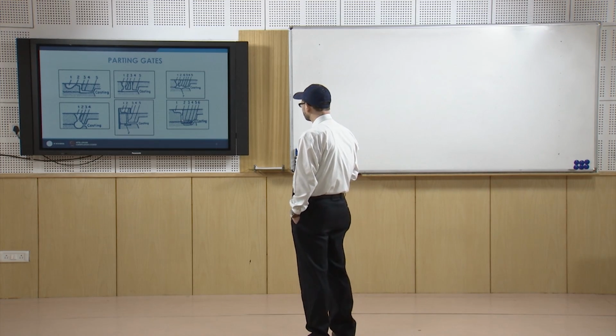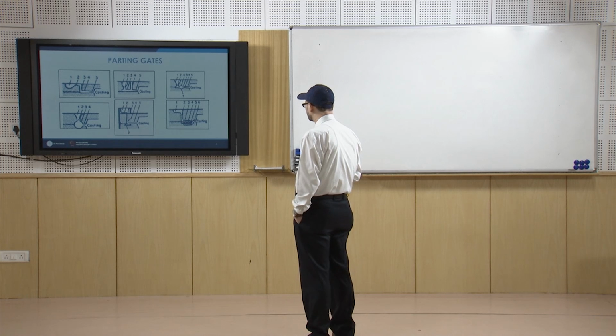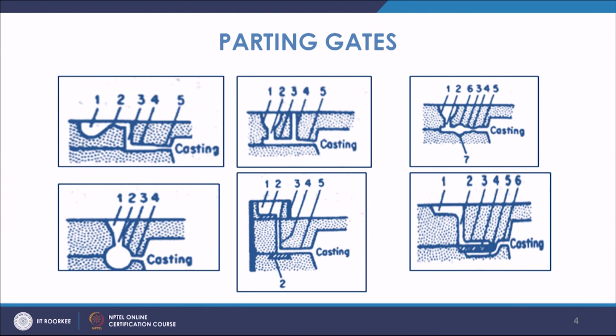These two figures show the use of core inserts. Now, in this case this core insert is used to filter the liquid metal. It will come from the pouring cup, and then this is a strainer core basically, and these are the splash cores. So, in this case you have the strainer core, which filters all the metal coming from here as it passes through, and then it will be fed to the casting.